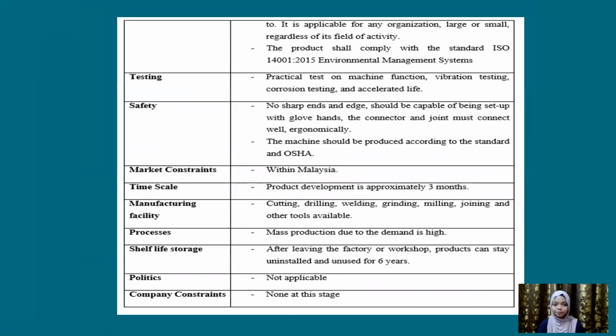For the testing, there is a practical test on the machine function, vibration testing, corrosion testing, and accelerated life testing. For the safety, no sharp end and edge, and it should be capable of being set up with a gloved hand, and the connector and joint must connect well and ergonomically. The machine should be produced according to the standard of NOSHA. So the market constraint is within Malaysia.